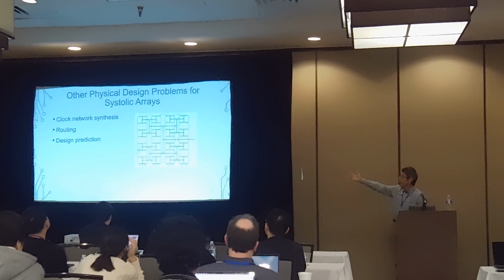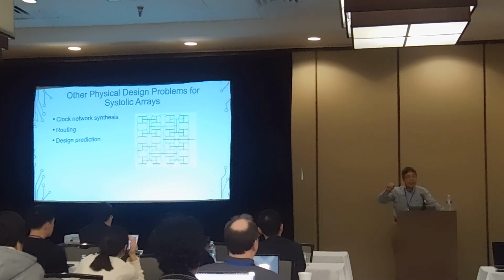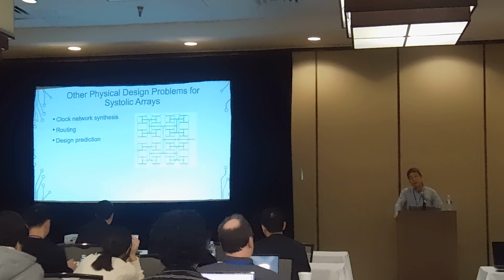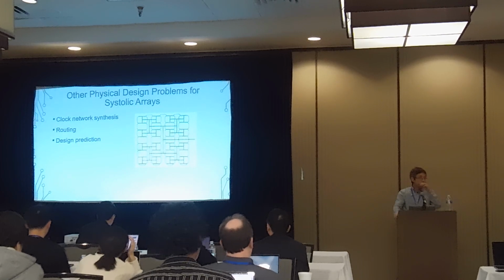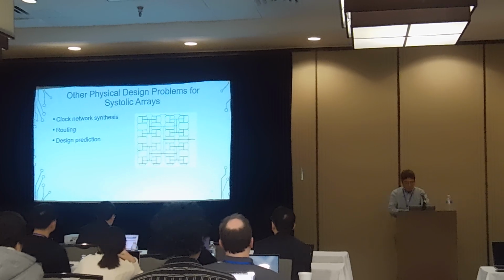But actually, I got this figure from the systolic array paper by Kung and Leiserson. They're not talking about clocking. They're talking about how, for systolic array, you feed the input from the boundary. Sometimes you need to do broadcasting, so this is a way to do broadcasting of the data. And also because of the regularity, I believe that can make the routing easier, and also design prediction, and even DFM, because there's a repeated pattern.